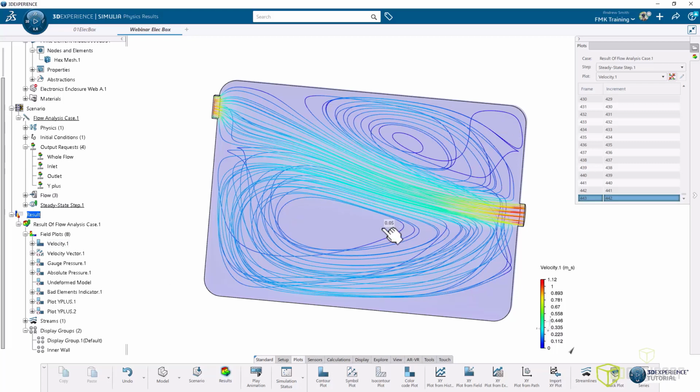And so, like I said before, if we were looking to put electronics in here, I kind of have a good idea. We probably would have had anyways, but I can see, okay, right here, I want to put my heatsink right where the flow is fastest. Right here would be a bad place to put anything that's going to be producing heat. And that's nice. It was obvious, but these are kind of the tools that we could use to get to that point where we could see that better. In later content pieces, when we have additional heat transfer happening here, we'll get into that more.